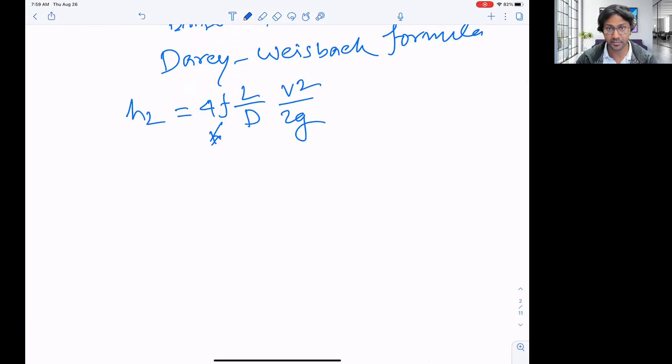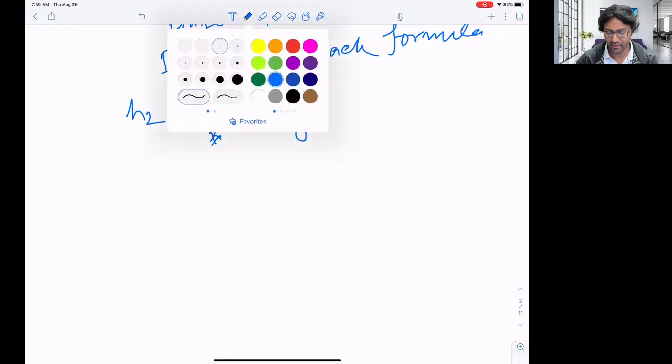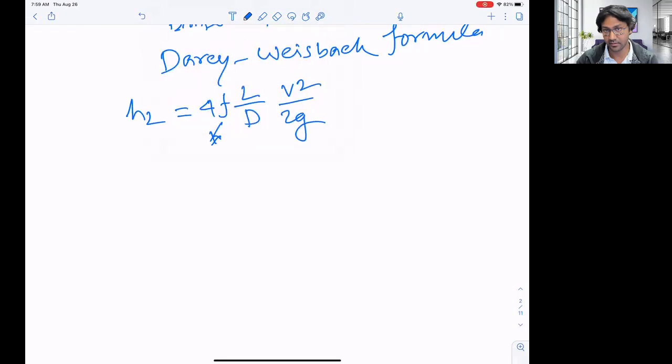If friction factor increases, meaning roughness increases, head loss will also increase. If the length of the pipe increases, that means we will have more frictional surface, and the head loss will also increase. And the diameter, if the diameter of the pipe is bigger, then what will happen? The water will face less restriction, then head loss will decrease. And for velocity, if you increase the velocity, meaning if you reduce the diameter, definitely water will flow very fast, right? And then the velocity head will increase, and if the velocity head increases, the head loss will also increase. So that is the relationship.